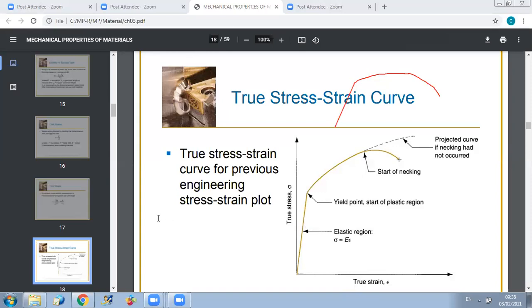Because in tensile tests, as we have defined together before, we have found the ratio sigma true over sigma engineering is equal to A0 over A. So we deduce that the true stress is higher than engineering stress because A0 is higher than A in a tensile stress case.